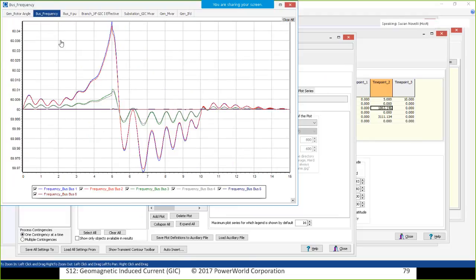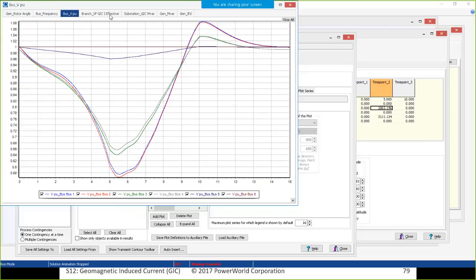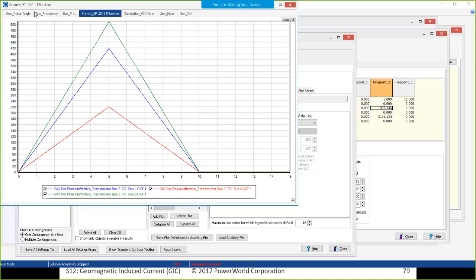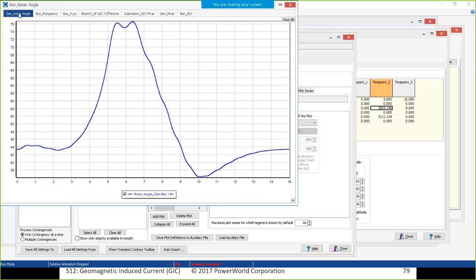Actually, no, this didn't collapse. I think it's with one of the different exciter models that it collapses, because we have the IEEE T1 exciter models in here right now. If you activated one of those others, like the AC7 or the AC8, I think that is a little bit less stable in terms of providing the VAR support.